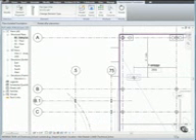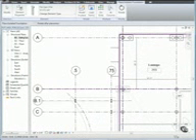Now pan over to grid location B1, and to place foundations on vertical grids, press the spacebar to rotate the isolated foundation. When you press the spacebar twice, the isolated foundation is rotated 90 degrees. Click to place it. Place additional pile caps along grid line 1.